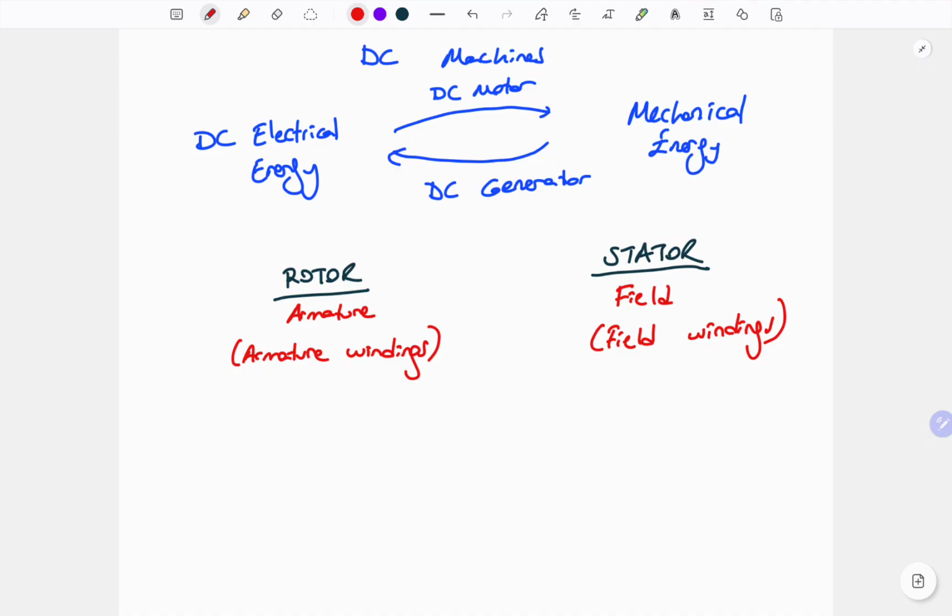In terms of the DC machines, we can say they have a wide range of speed and power. Because of this, in different applications, we can see the DC machines as motor or generator. When we compare with similar power ratings of other types of machines, they are efficient and have superior torque characteristics. Because of this, especially in railway and EV vehicles, we can see DC motors controlling the systems. But they are expensive when we compare, especially with induction machines.